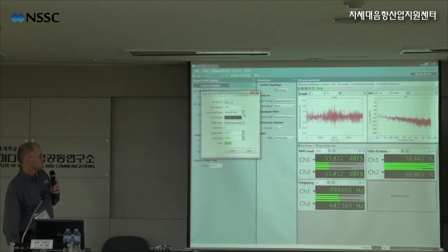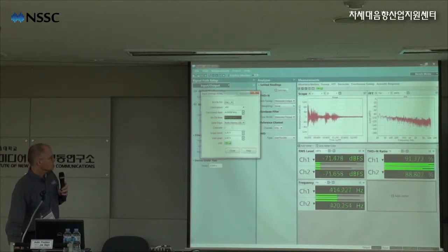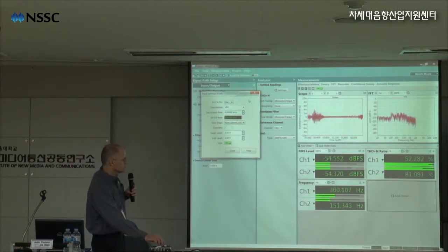Let's see how low we can go here. Oh, we can go down to 4 kilohertz, which is the lowest limit. But these microphones, I think, are meant to operate at a higher limit. So if we're at 4 kilohertz, the bandwidth of our system is going to be less than 2 kilohertz, as you can see here. Let's see if we can still measure a signal.